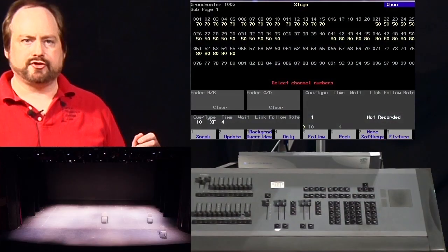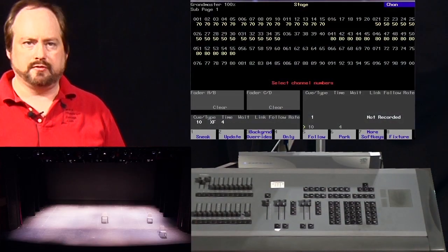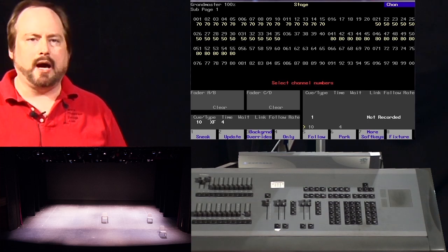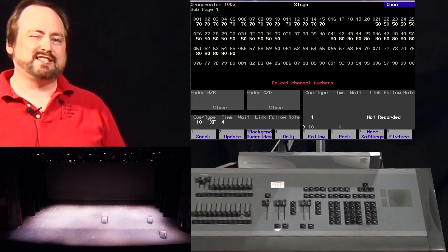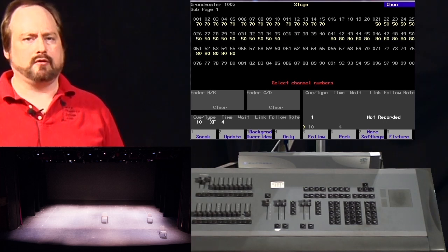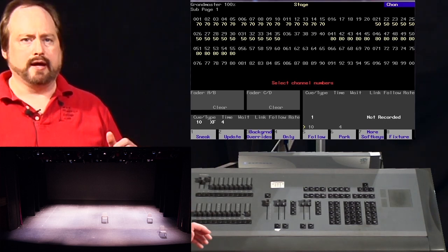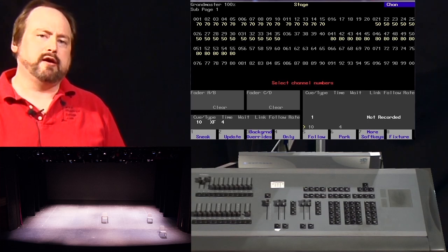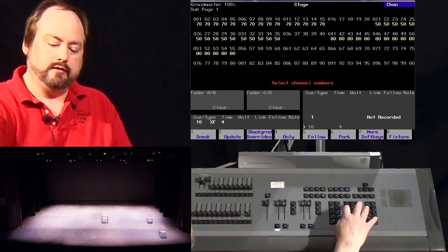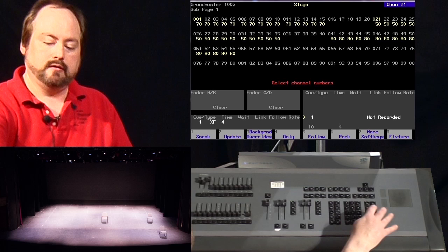Right now our sliders are still up from where I put them for our Q10. Well, let's say that we wanted to modify one of the areas who has a channel already up. We can set that channel to be a specific level, and that setting will override what the submaster is telling it to do. So let's bring area A to full. Channel 1 and 21 at full.